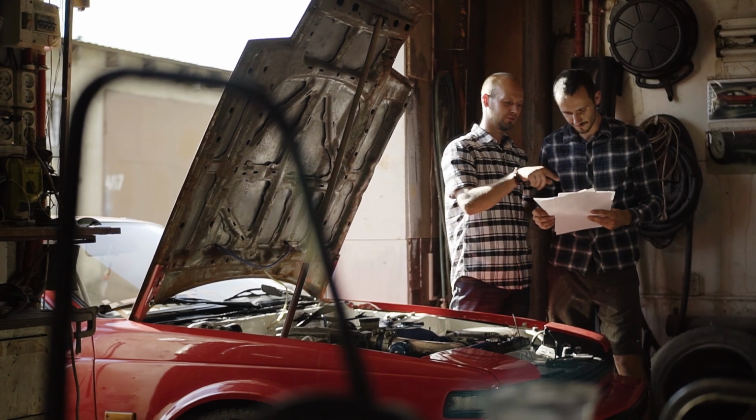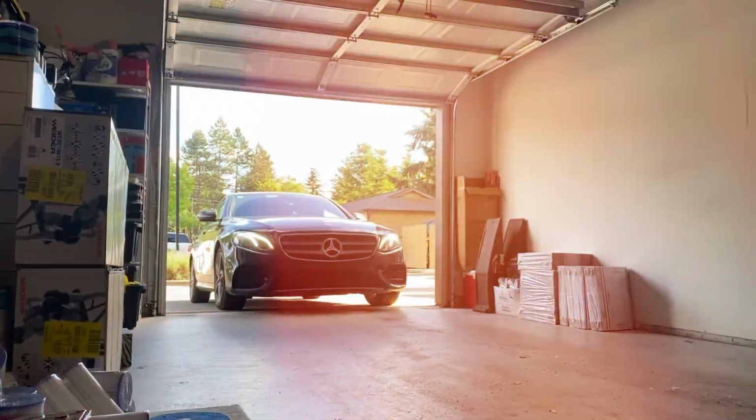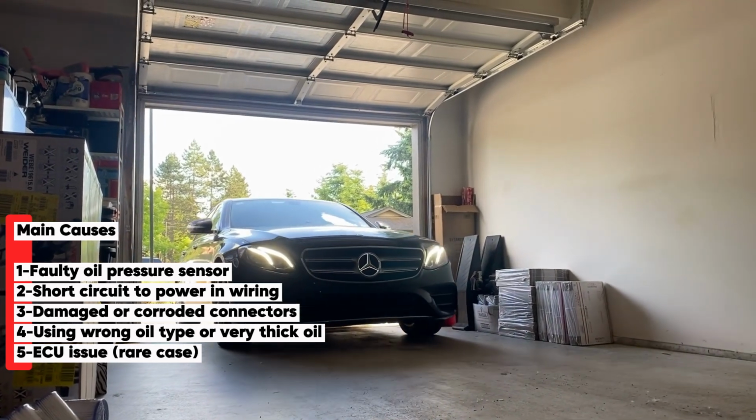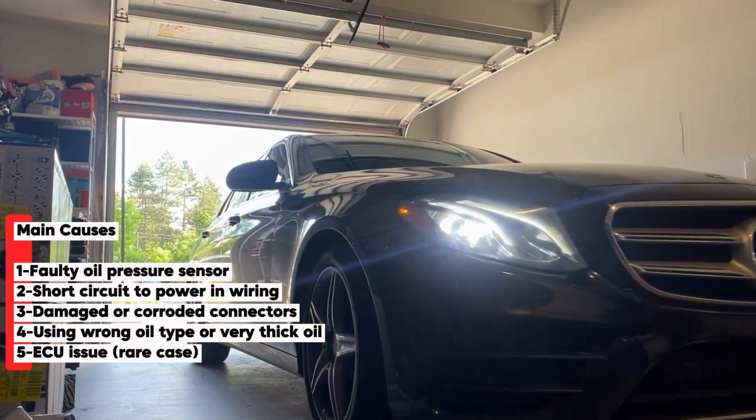Here are the most common causes. 1. Faulty oil pressure sensor. 2. Short circuit to power and wiring. 3. Damaged or corroded connectors. 4. Using wrong oil type or very thick oil. 5. ECU issue, rare case.